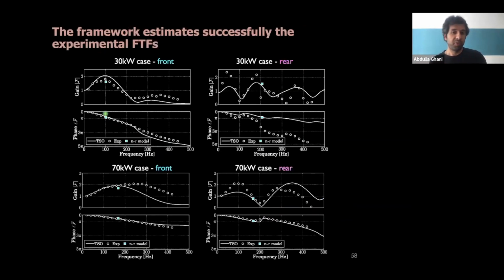The flame transfer functions that they have measured are the circles from the experiments, and the white line here is the estimation of the model, just putting in pressure time series recorded from the experiments and rebuilding in a one-dimensional acoustic network model the cavities and the system as a geometry. That's it. You put these 2 things together, you let this machinery work, and then, of course, you don't have a 100% agreement, because this is not feasible with something which is just estimating.